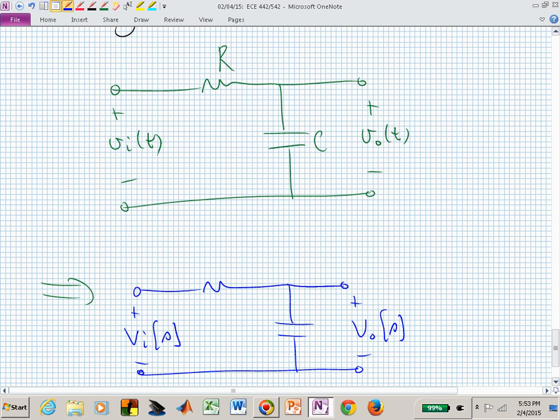What does R do when you transfer that from time domain to frequency domain? It turns into an R, doesn't it? It went into the phone booth and came out the same as it went in. Didn't have to be a superhero. But what does change in this circuit? The capacitor, doesn't it? That's an energy storage device. It does contain an S variable. This is now 1 over SC,